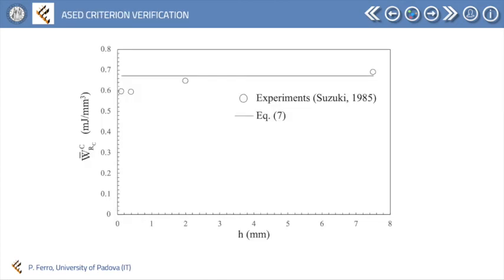The analytical value of the strain energy density to failure averaged over a control volume of radius RC was compared with experimental values calculated by using a numerical model, the experimental nominal stress to failure as a function of the adhesive thickness. Results are shown in this figure. It is observed a maximum deviation from the theoretical value of about 12% that may be caused by statistical uncertainties related to experimental data. To date, it can be concluded that in first approximation, the critical value of the average strain energy density parameter is adhesive thickness independent and can therefore be used for bonded joint design.